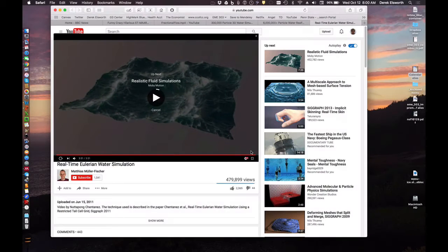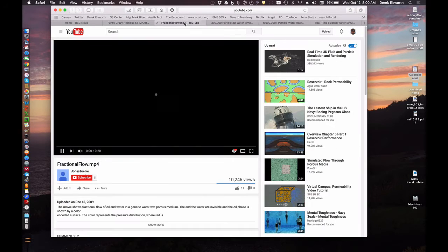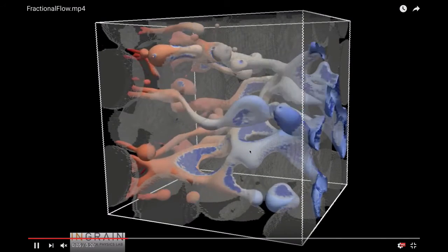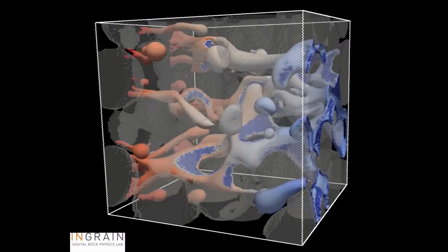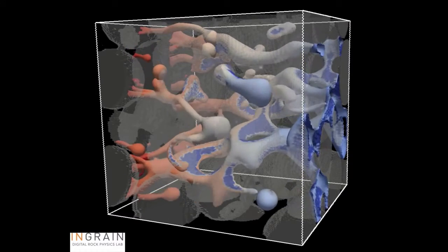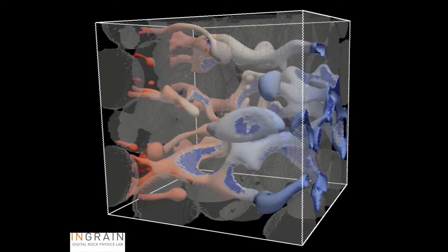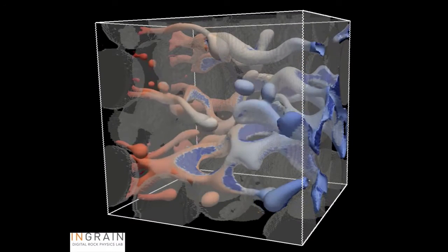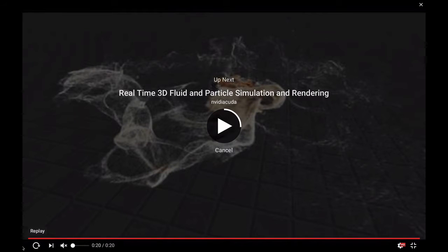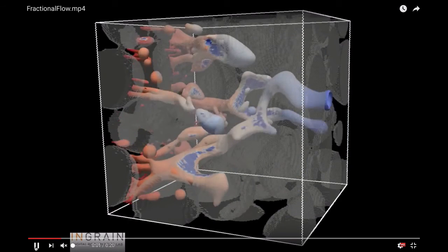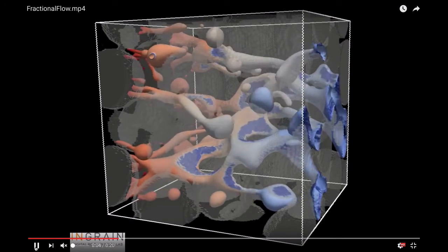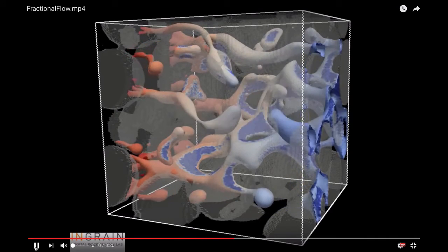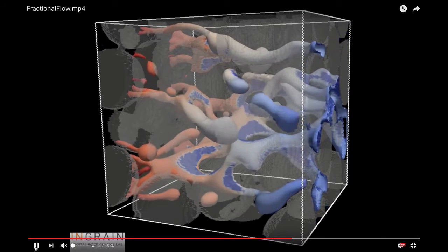Some flow systems are much, much simpler than that. And perhaps, if you're a petroleum engineer or an environmental system engineer, for instance, then you're dealing with fluid flow in porous media. And so the previous simulations we looked at solved for conservation of momentum. So throw a ball at a wall, it hits the wall, bounces back. You're conserving momentum in that case. It's this v squared over 2g term that's in Bernoulli. In some flows, for instance in porous media flows, the velocity is so small that compared to the other terms, the pressure head and the elevation head, it's trivial.